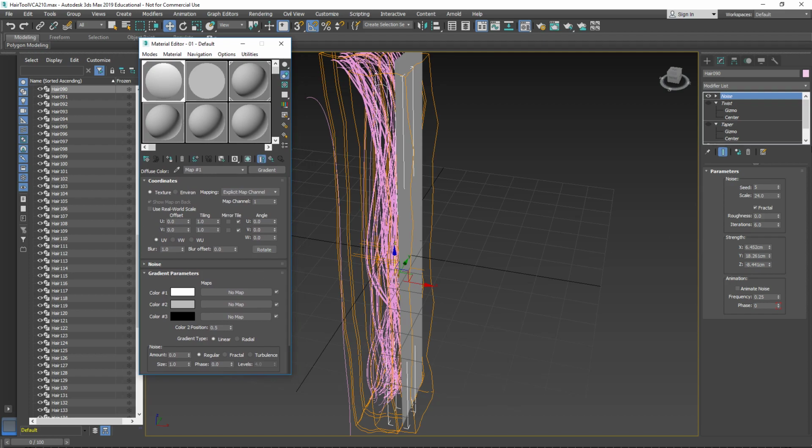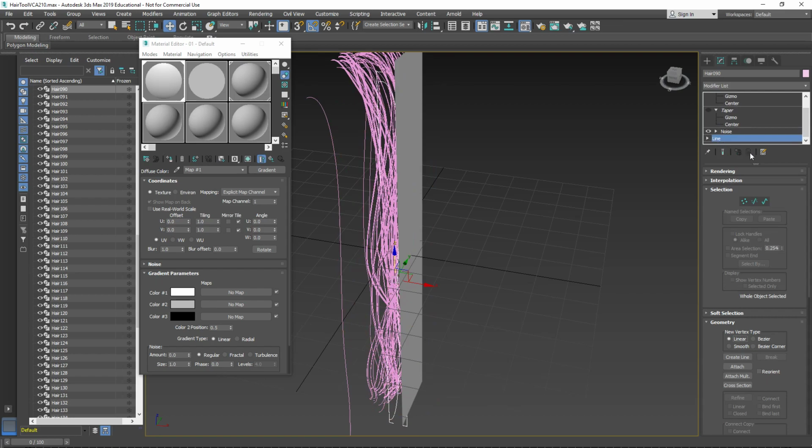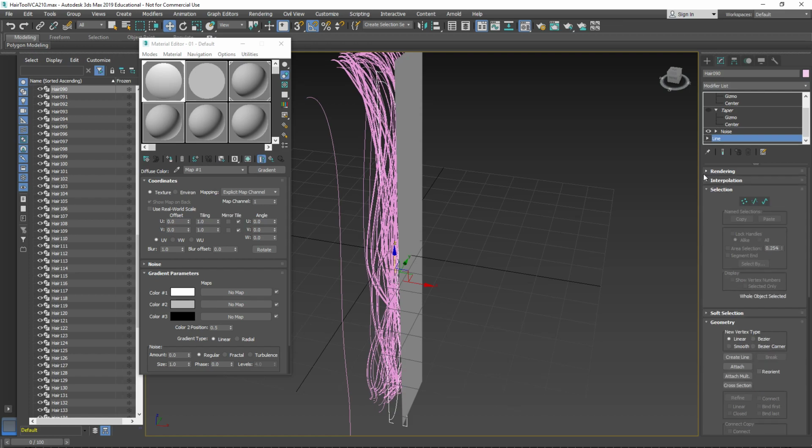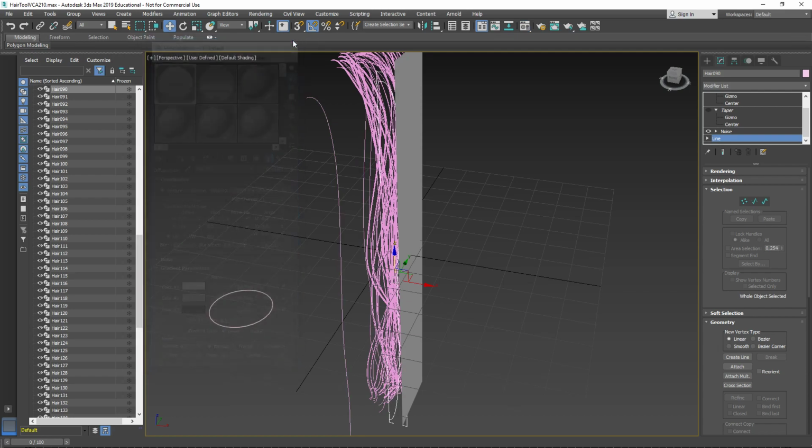So when you generate the line, if I go over to here, line, you need to make sure that when it is generated, it has UVs. There it is, generate mapping coordinates. Those mapping coordinates will fill the UV space. So that means that that gradient will then go from black right at the top to white right down the bottom. So that's the easy one.